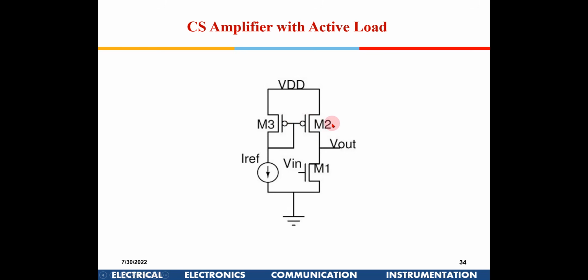Just think over it. I can see this is a Pmos, right? Once we decide what the current is, how to set W by L? Just use the ID equation, and set the W by L of this transistor so that this ID follows here. VDS is known, so we can set the ID equation.